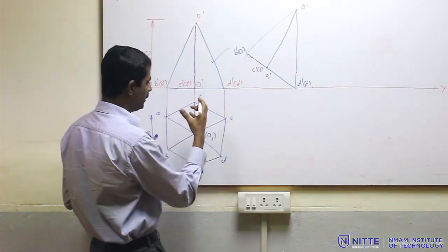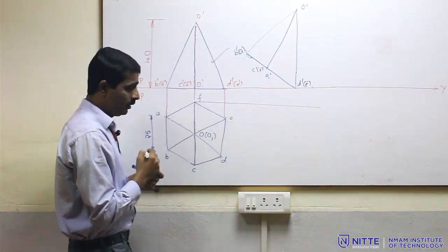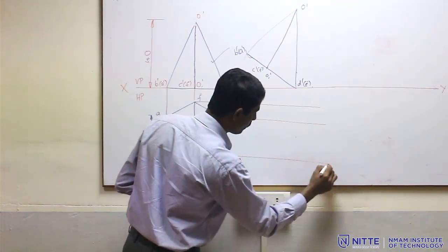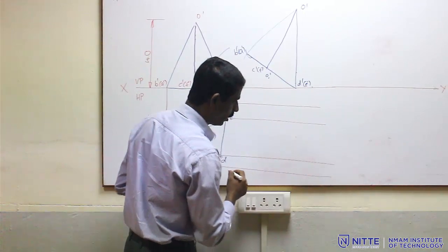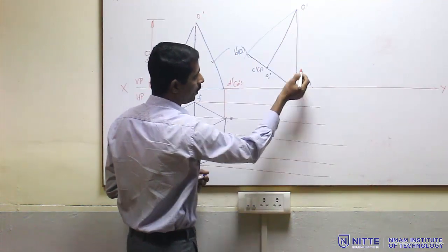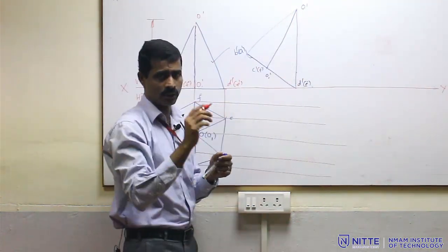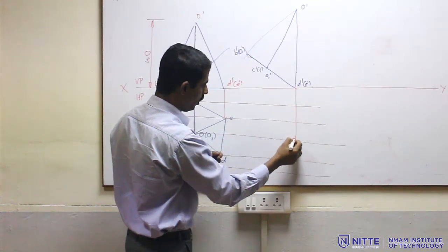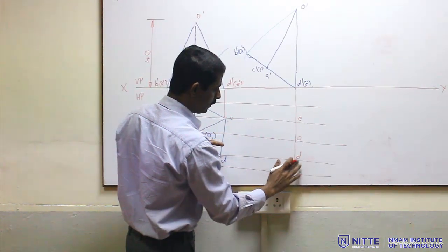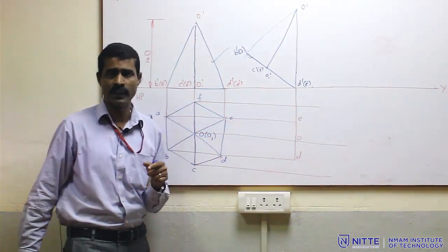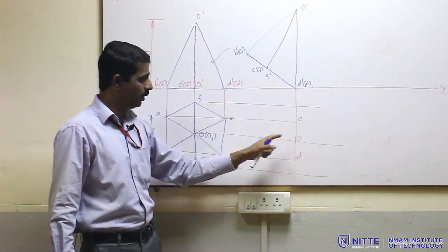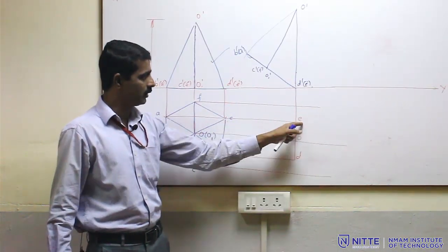So, draw the projection lines. I have F projection, A and E projection line, then I have B and D and C horizontal as well as O horizontal. Then I project from the top ODE which is perpendicular, so it is on the same line. So, I go for O here, E here and D here. I will get 3 points on the same vertical line, because O dash, D dash, E dash is a 90 degree or vertical line. So, I get O here, D on this point and E on this line.